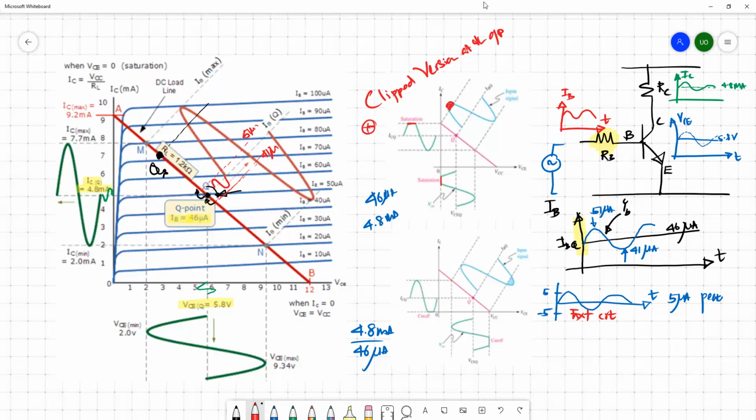Similarly, if you place your Q point close to the cutoff, like in the second figure, then with the external input you feed to the circuit, there may be a high chance of having this kind of region. So your Q point is pushed into the cutoff.